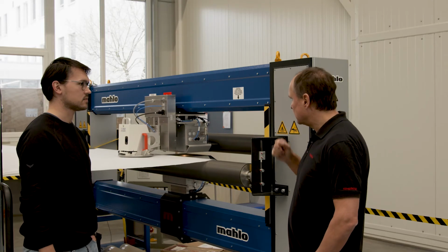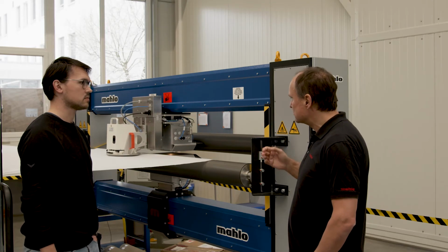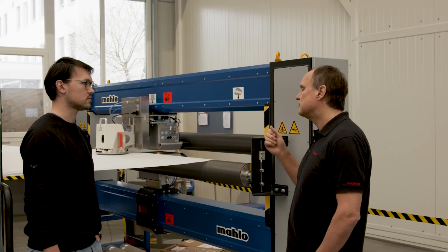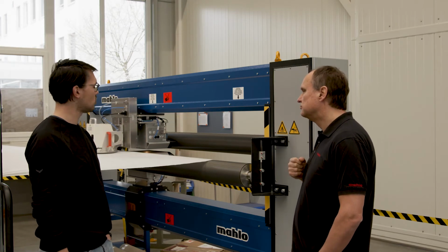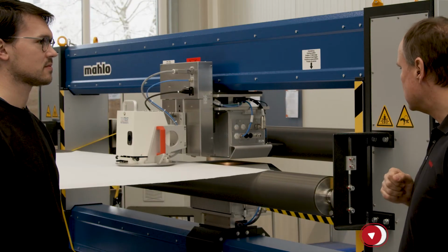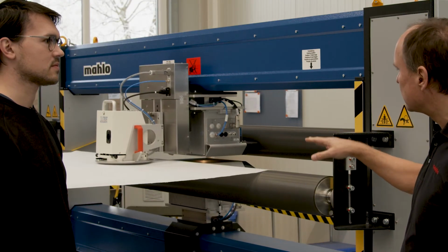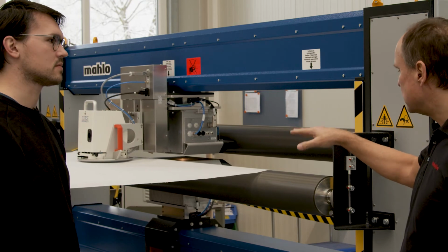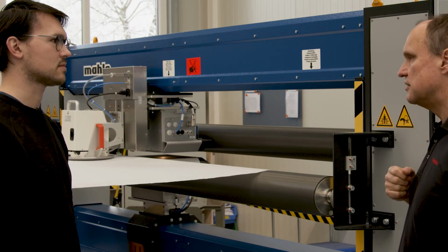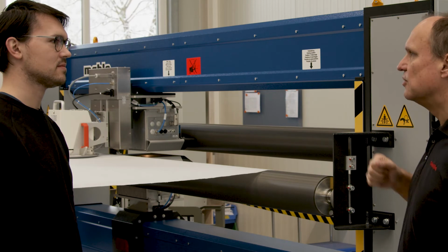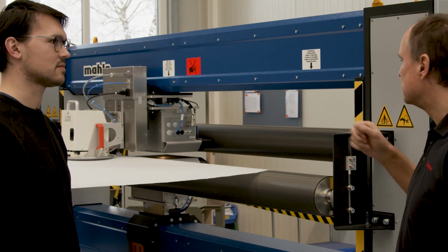Okay. And by the way, is the web speed limited to this type of measurement anyhow? No, not really. If your moving speed of the web is up to 500 meters per minute, it's also possible to measure the air permeability of it. No problem at all here. Okay. But one thing is important, we must take care that the web is stabilized underneath the sensor, so it may not drop down or swing up and down or something like that.